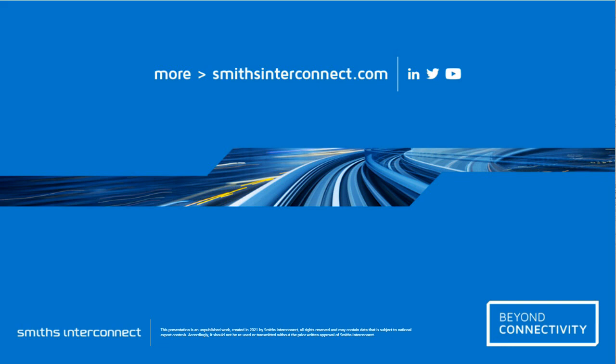Yeah, so it just really depends on the application. For vibration, your typical 20 Gs, 10 hertz to 2,000 hertz. We've tested multiple designs in those environments and have had no issues with any intermittencies or anything like that.